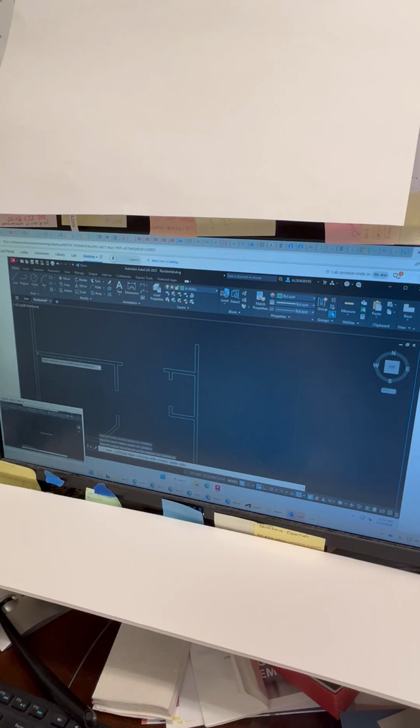Over here, the trim command acts like an erase command too, even though it doesn't have any sort of boundaries or cutting edges. So you can delete this little line here before you start trimming the linen closet. All right. And so now just go around, and you don't have to use a fence. You can still just individually click if you're more comfortable doing that, like I'm doing here.